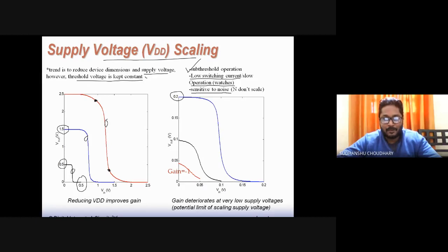That is, a small noise can even affect the voltages at the internal nodes of the circuit. So the circuit is more prone to noise when VDD is very small, and also less robust. That is one of the disadvantages of operating CMOS circuits at low voltages.